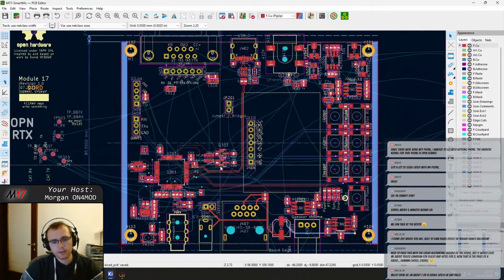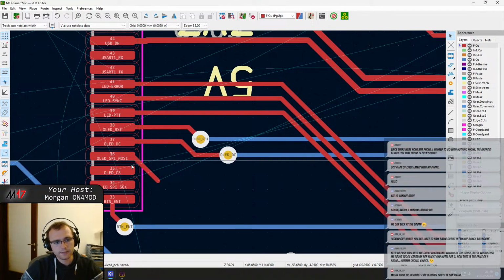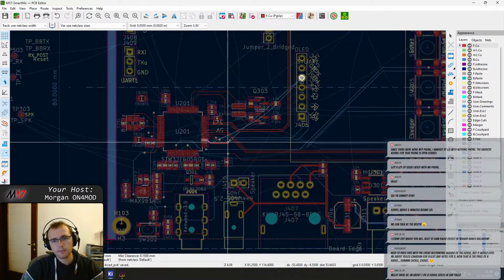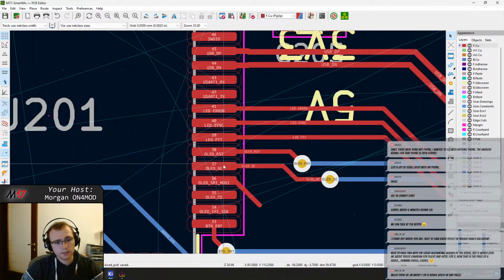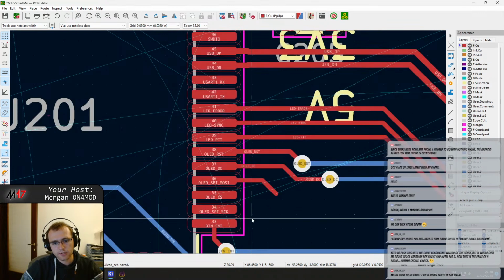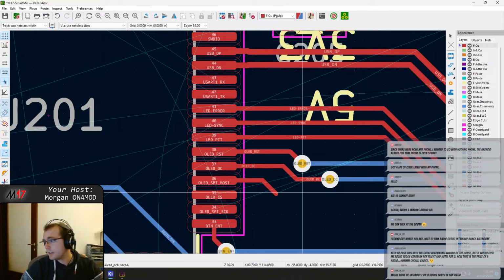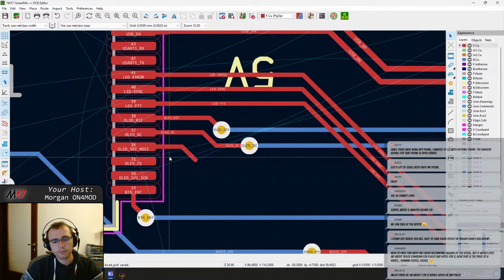Maybe, yeah, okay. We will do now the OLED, yes. SPI MOSI and SPI clock, and yeah, chip select. This can be routed later. It's not critical, but those two need to be routed carefully. We don't have any OLED MISO, I guess. We don't read anything from the screen. Let me check quickly. Nope, we don't.